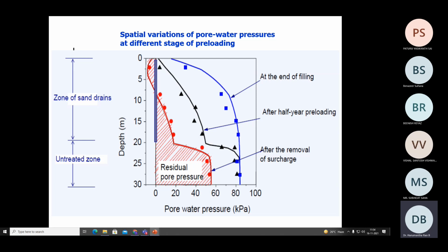Only then can we back calculate the degree of consolidation that we have achieved with time. Initially when we designed, we assumed different parameters. But when you execute the same design in the field, it should be assessed by measuring the parameters, not with the design. That's why it is called verification of the design. So this is all about your PVD technology.